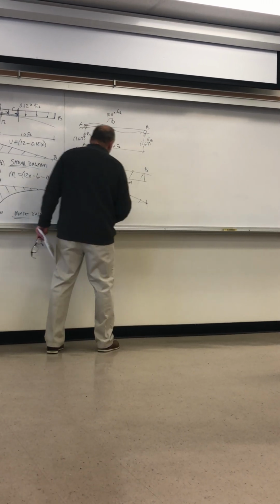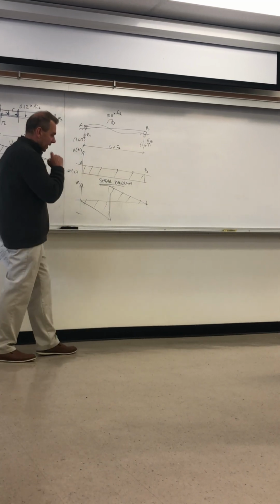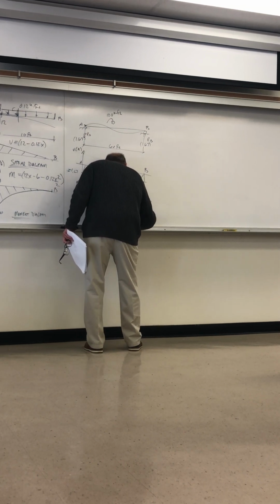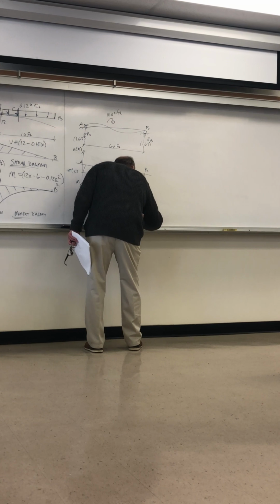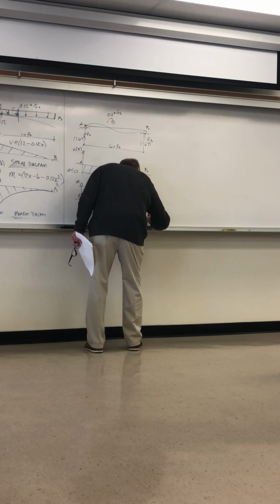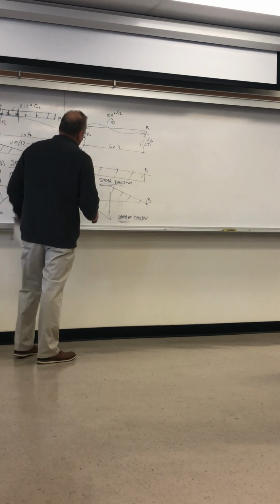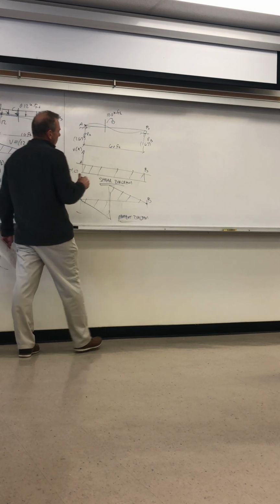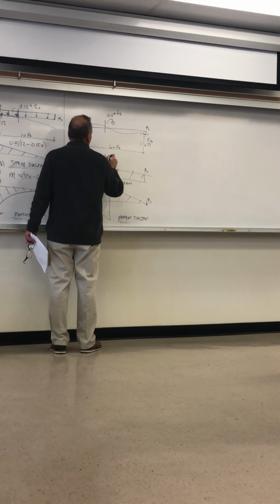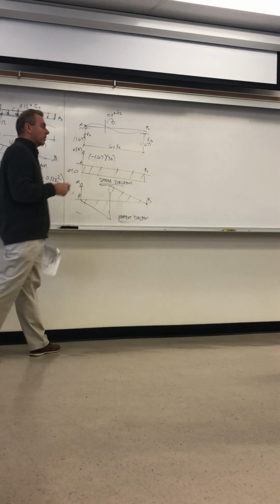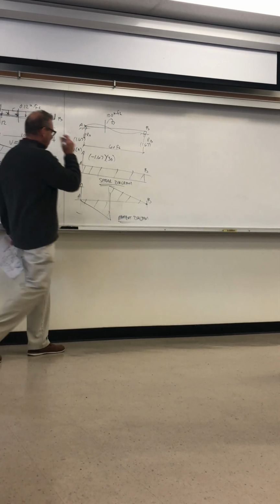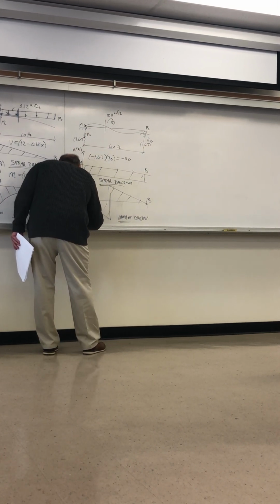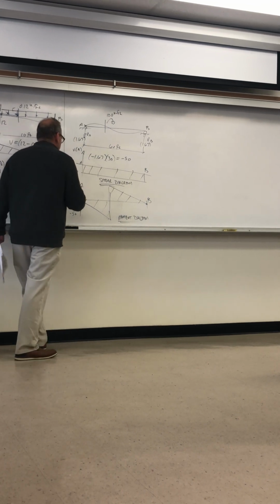And you just have to calculate 1 point, well, 2 points. This point, this point. This is your moment. A, B. And this value there, if you take a cut just before the moment there, it's minus 1.67 multiplied by 30, 30 minus the differential distance. So that gives me the minus 50.